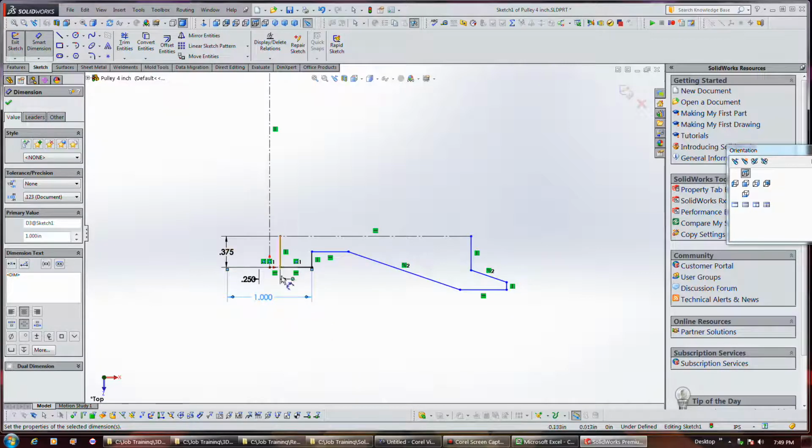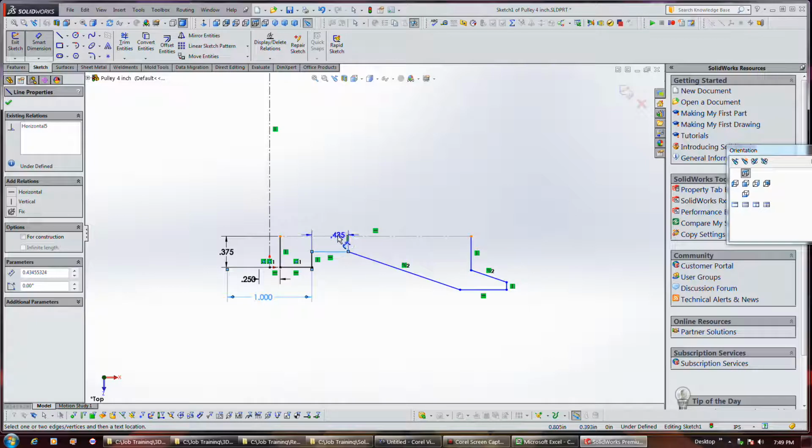So I guess it knows that center line is diametral because I selected it, so it knows what that means, that it could be a center line. And of course you can do those types of dimensions vertically too, because it looks at that, that's a part, it's a midpoint construction line, still treats it like that.